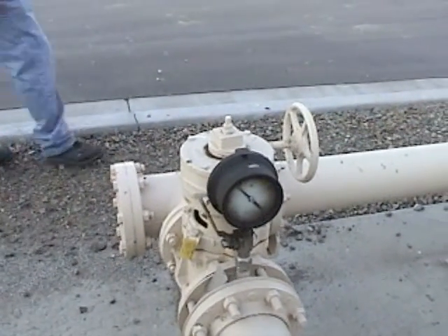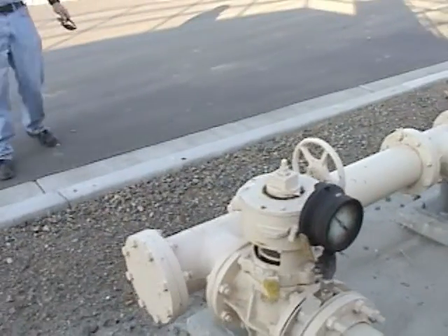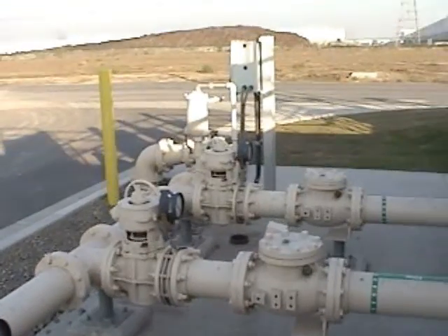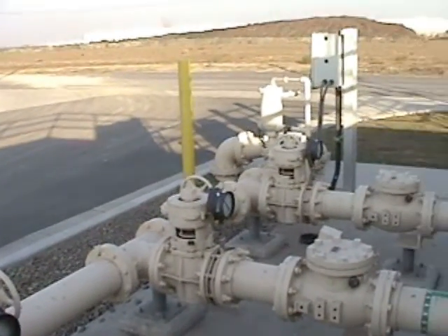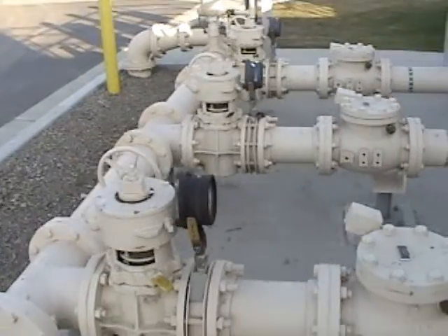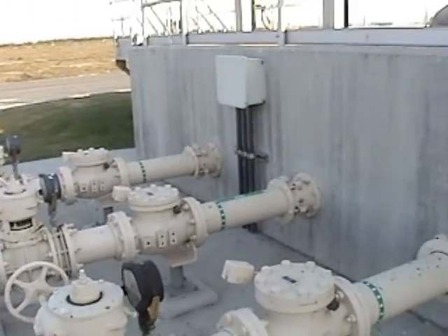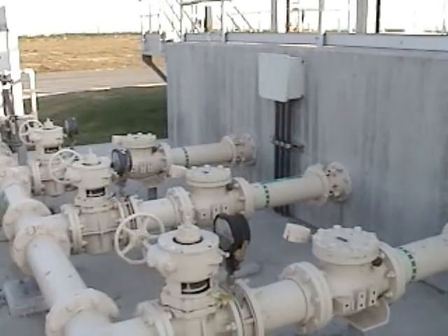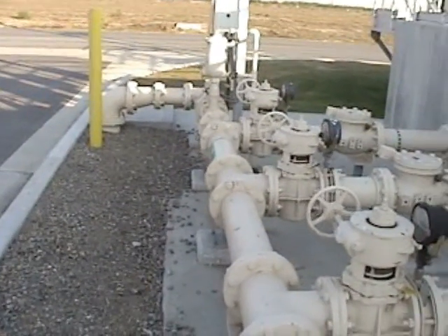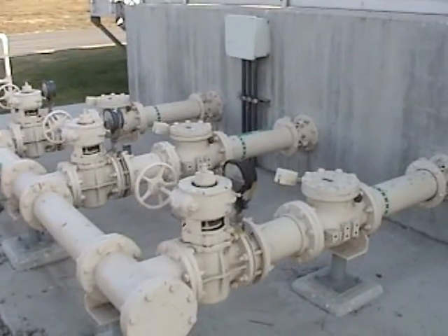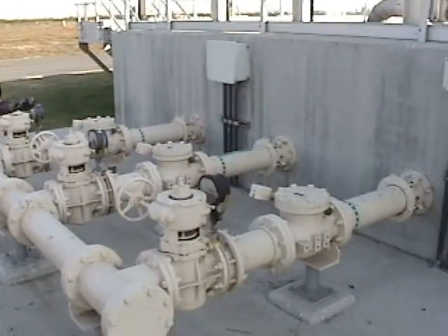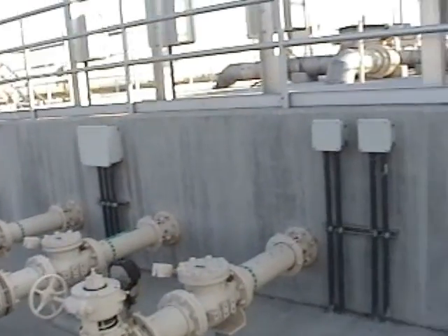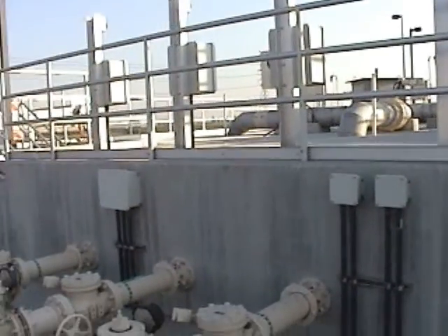Some of the things you want to watch for is if you get an alarm on the SCADA system and it says high high recycle water wet well, that is indicating that one of these pumps is either not adequate and another one needs to be placed online, or they have malfunctioned and one of them has failed. You'll get several alarms. If one of these fails on high motor amps or high temp or whatever, you'll get an alarm for that. But typically what we'll see is a high recycle wet well level alarm.